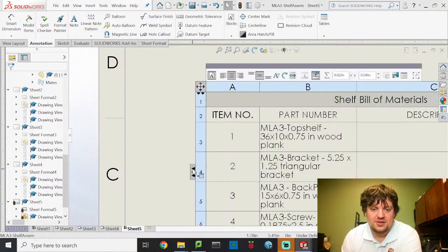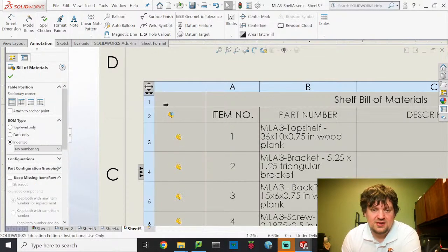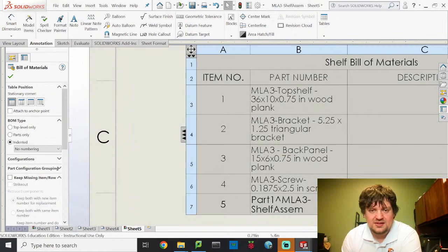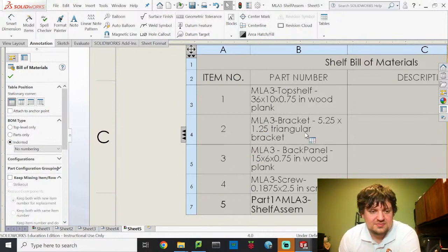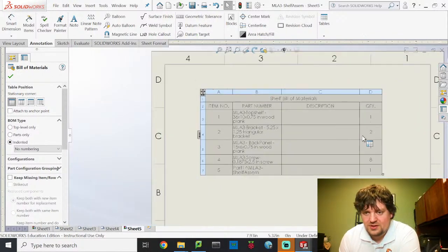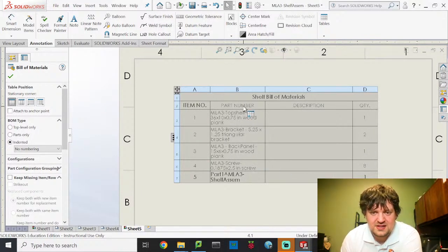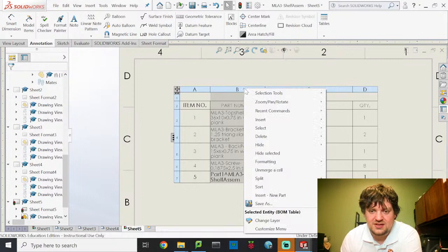Thank you. If I click on this arrow, it will pop out a column here that shows me this is an assembly. These are parts, parts, parts, parts. Okay, so it's kind of interesting. I can pop that back in. I don't actually need to have that. But over here, this is nice because it shows me the quantity of each one of the pieces that I need. Now here, I don't actually want this column to show up. Quite frankly, this column is kind of dumb.